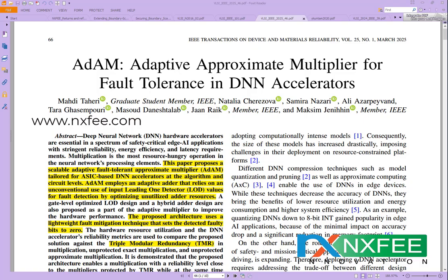While effective for DNN reliability, the adaptive fault-tolerant approximate multipliers introduce deterministic approximation errors, rely on limited carry lookahead adders and triple adaptive adders, and mainly focused on ASIC implementations without extensive FPGA exploration. To overcome these restrictions, we propose a hybrid logarithmic multiplier that employs a variable truncated and a variable higher order shifting method with an adaptive parallel prefix adder.